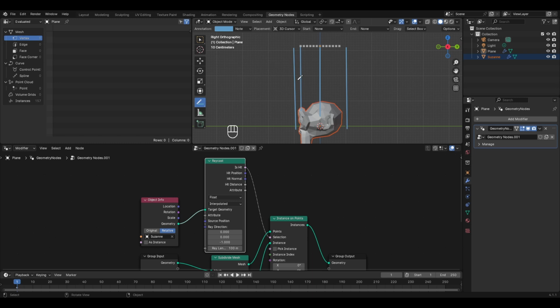Now for deleting these annotations, again I'll go to the toolbar, hold down the left mouse button on the draw tool and select the annotate eraser, then left click and drag to remove it. And now let's go back to the select mode.